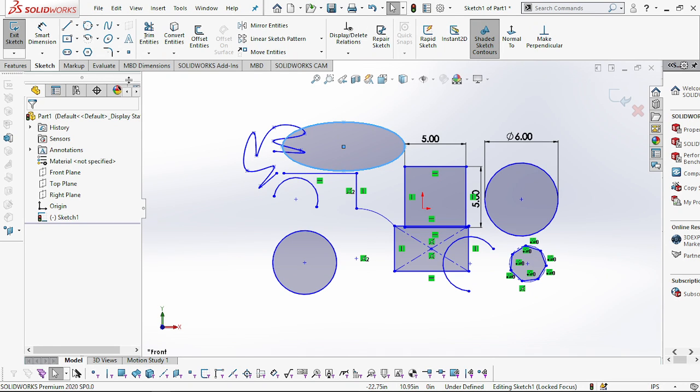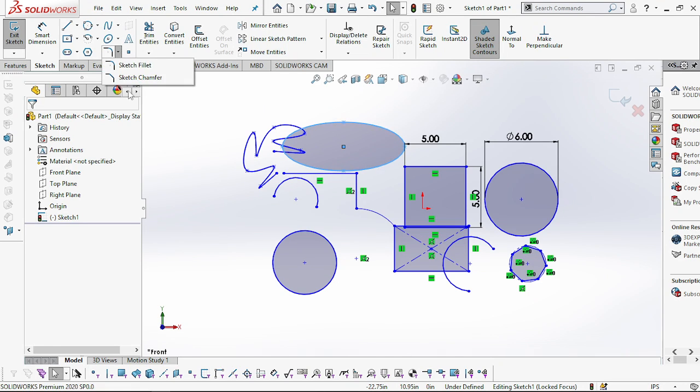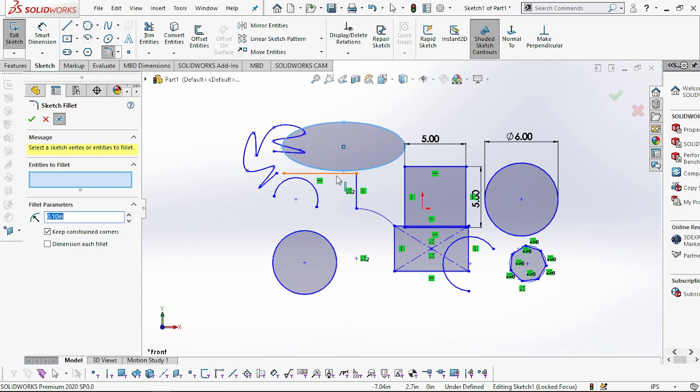After there, we are going to talk about the fillet. The fillet has two options. There is a chamfer and then there is the sketch. So if I just press on the sketch, I come and select the first point, the second point, come to this side, and under the arrow box, select the diameter or the radius of the fillet. Just increase it as you are seeing your work. So if we give it 0.5, press